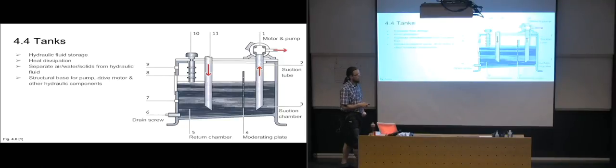So that when you're doing checks here to see how much water you've had in your system, how much water has been divided up from the hydraulic fluid, you can actually open the drain screw, and then the first thing that will happen is that you will probably get a stream of fairly clear water coming out, and then hydraulic fluid is going to start getting mixed into the water, and then you can close the drain screw again, because then you have drained most of the water that was in the bottom of the tank. So it's a very quick way of getting rid of water in your hydraulic fluid.